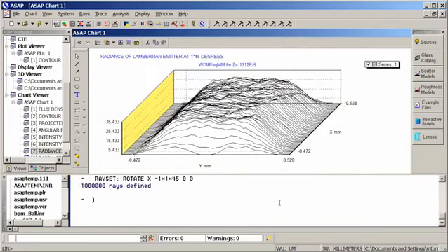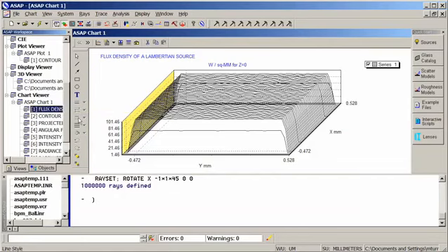Okay, and let's take a look at some of our analysis. The flux density, by default, the emitting rectangle is Lambertian. There is also an ISO option that you can just type at the end of it if you want isotropic data. You could also have applied an apodization function to the data. But this is what I would expect for the flux density of a Lambertian source in watts per square millimeter.